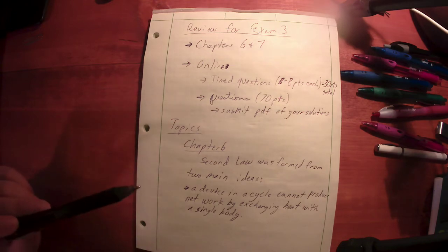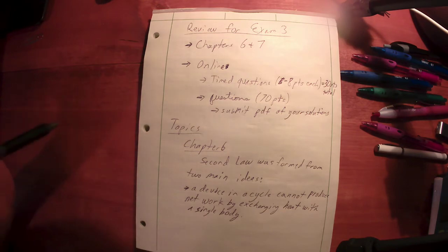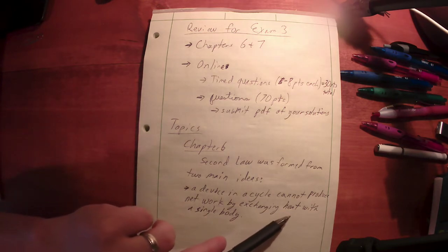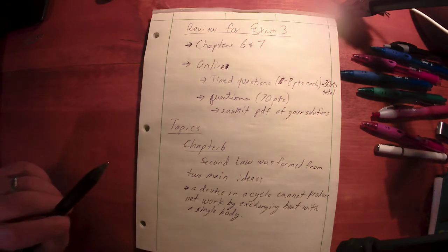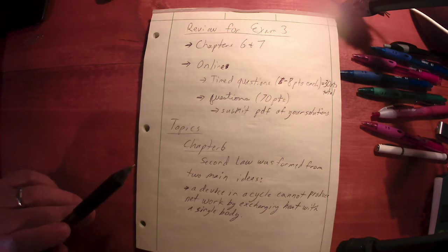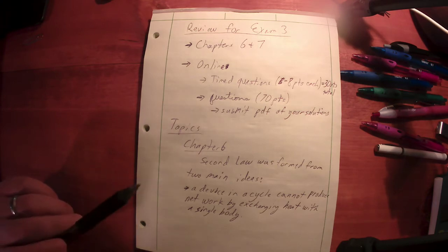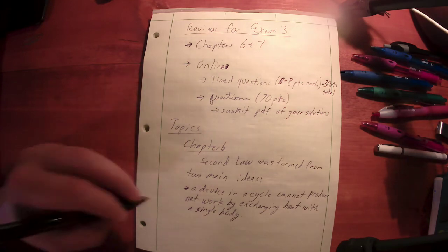I have to reject the remaining heat that I couldn't convert into work to another supply. So that could be the other thing that I'm doing. I could be rejecting heat to a second body. Right? That's quite possible. But I cannot have a device operating in a cycle repeatably with only a single heat reservoir. I'm going to have to absorb heat from one and reject heat to a second one.